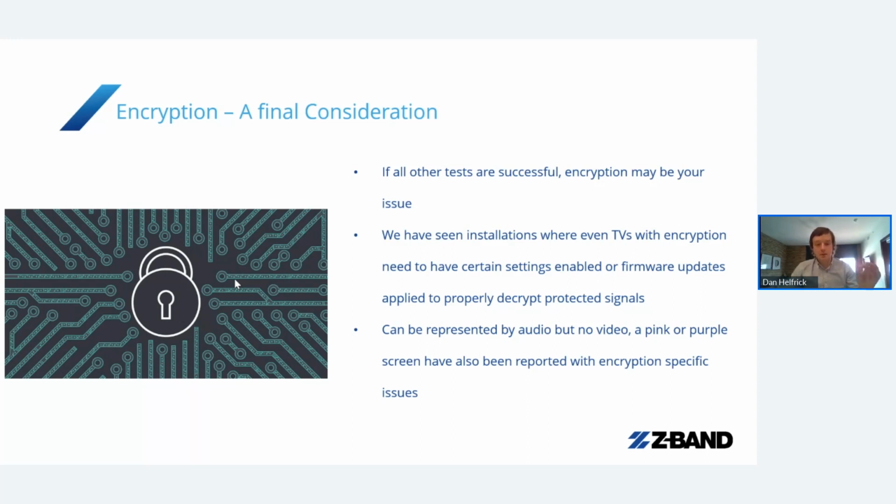So there is this fourth consideration here that I tacked on at the end of the presentation, where if your power is good, if you know you're troubleshooting the right channels, if you know that your video quality is where it's supposed to be, and you still have nothing, then we might be looking at an encryption issue. And I always like to keep that in the back of my head when we're troubleshooting with clients. But those are the big things. And like I said, I tried to keep this bite size, half an hour, monitoring and measurement.